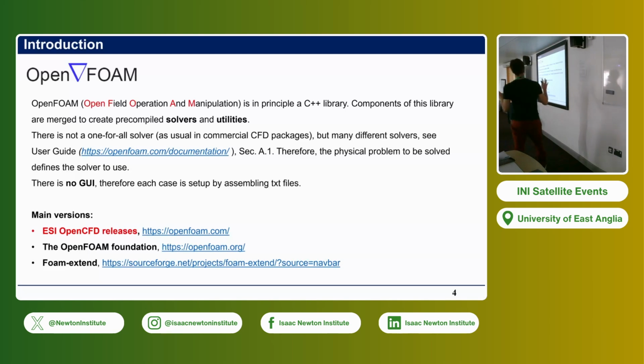So there are all the libraries to solve different kinds of equations, and the solvers put together these libraries to achieve a certain kind of flow field. And so you need to know the physical problem you want to solve to decide which solver to use, which equations to solve. There is no graphical interface, so everything is assembled by putting together some TXT files.